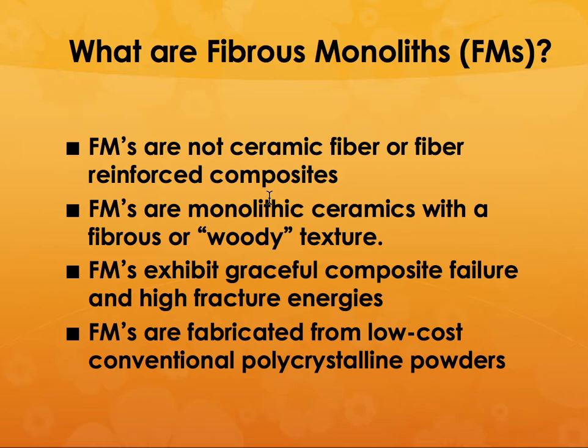So they are not ceramic fiber or fiber reinforced composites. They are monolithic ceramics with a fibrous or woody texture, and they still exhibit graceful composite failure and high fracture energies. And it can actually be fabricated from low cost powders, and it can even be 3D printed. So that's one big advantage with these materials.